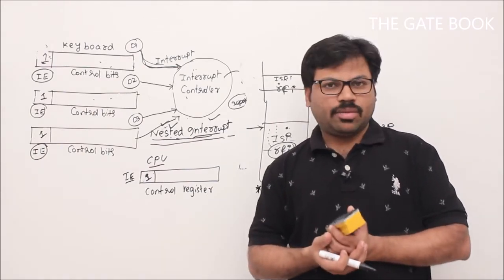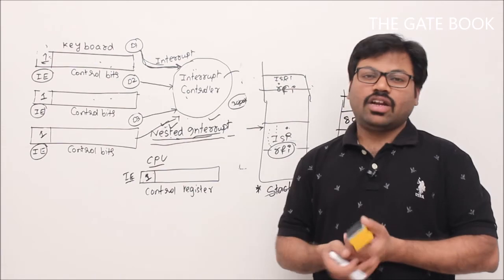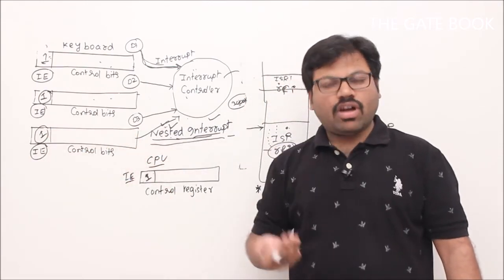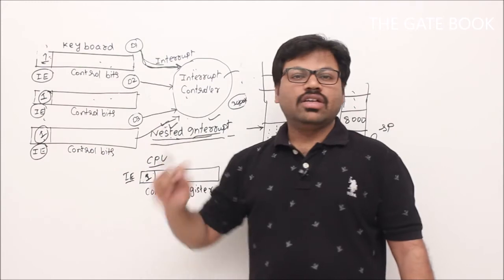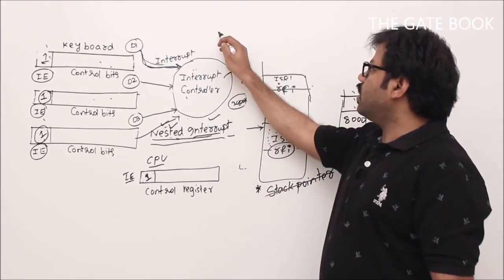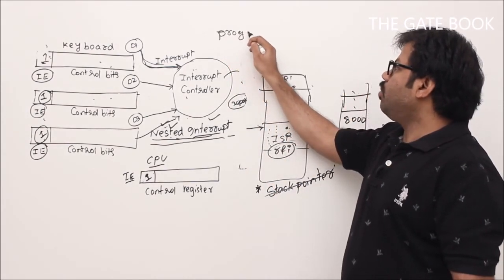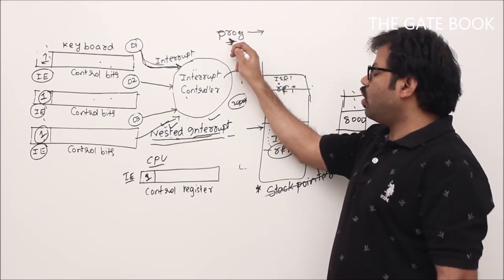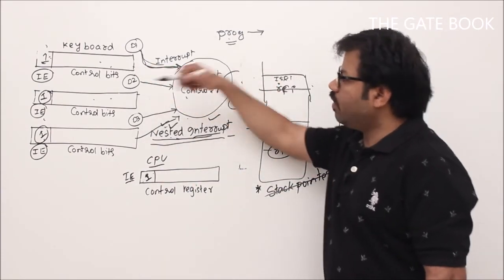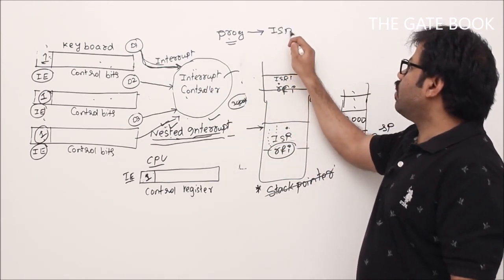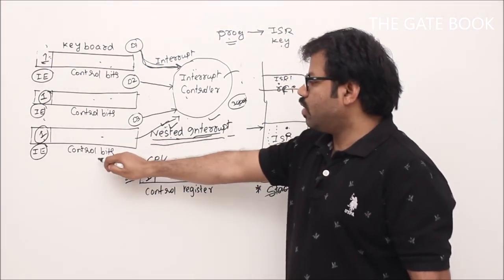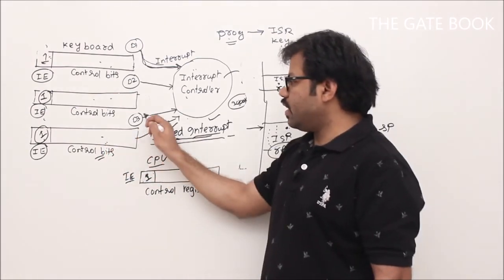Finally, you understood about nested interrupts. The single interrupt mechanism is easy, correct? Now for nested interrupts, what do we have to do? We have to make the IE bits 1 first, right? The program which wants to have nested interrupts should make the IE bits 1. Sir, but in nested interrupts also I want a restriction. What is that? Let's say I'm executing a program that wants every interrupt from every device. Then suddenly the keyboard gave an interrupt. Now I'm executing the interrupt service routine of the keyboard, but the keyboard only wants interrupts from this one register. What is the device? D3, not from D2, sir.